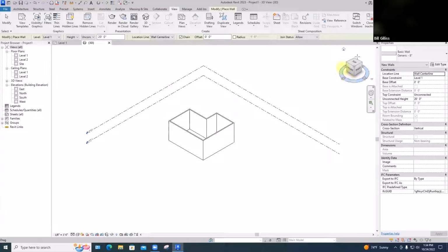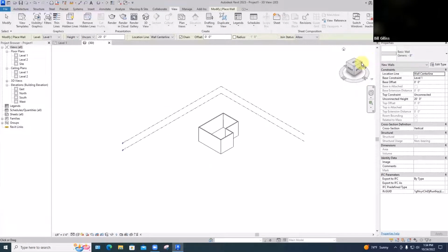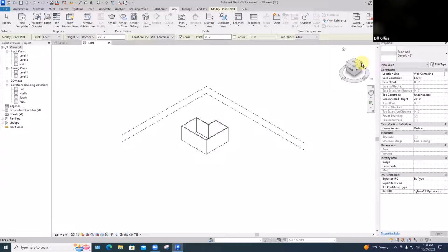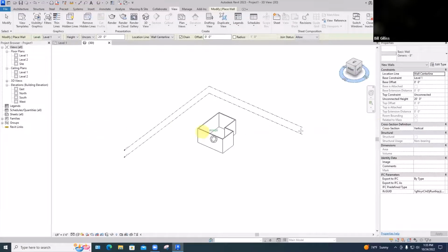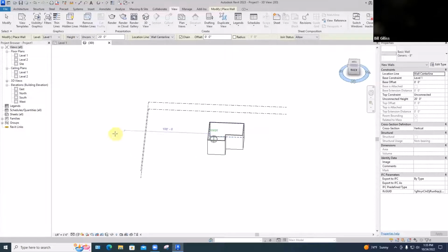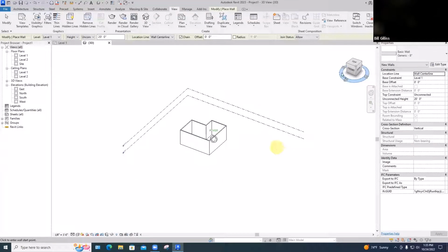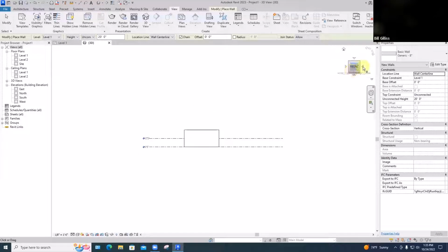And then over here, we have this same view cube that we had in AutoCAD to be able to see and rotate stuff in 3-dimensional space. We're clicking on different corners. It'll take you around like that. And if you drag and highlight over the moat, I guess you call it, click on that and drag, and then you can rotate around this way. And that's just technology. Either they borrowed it from AutoCAD or AutoCAD borrowed it from them, I forget. And then clicking on any of these faces takes you into that elevation view. Or the top view, either one.